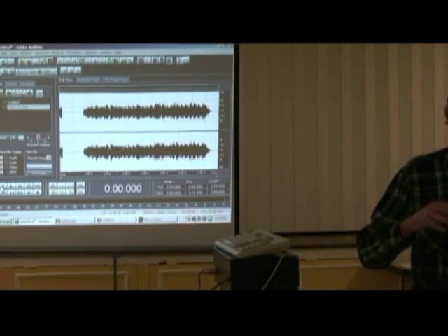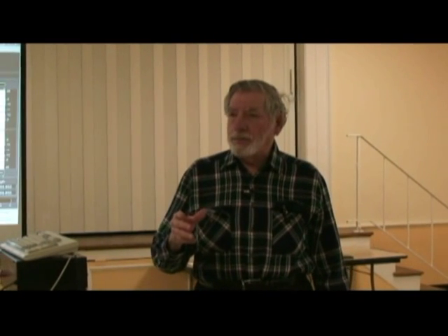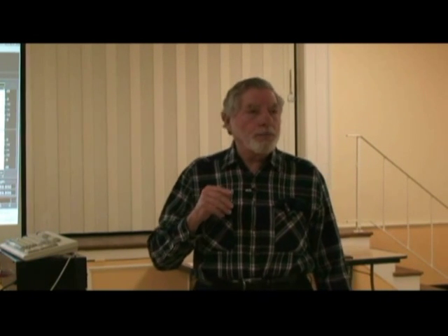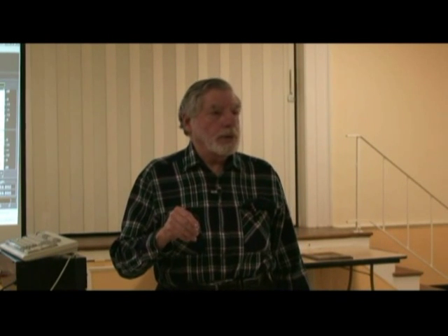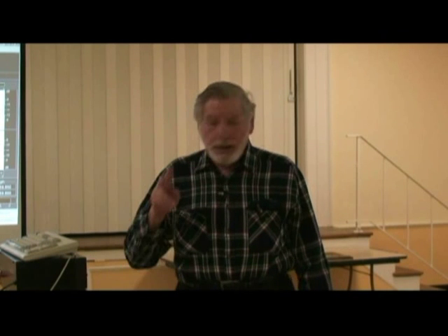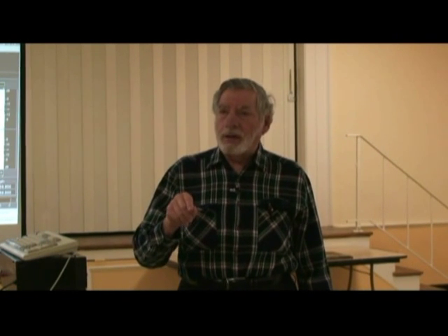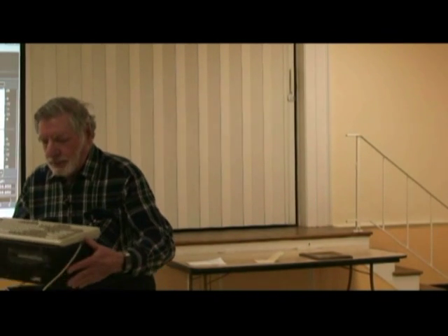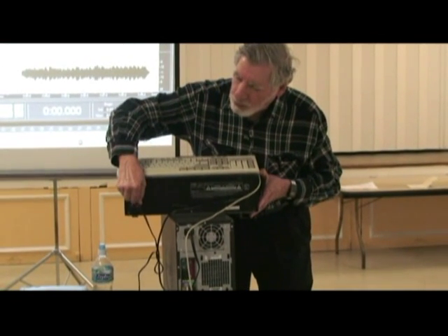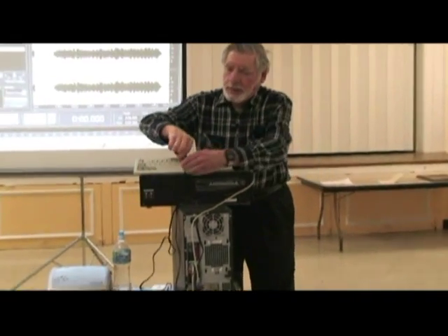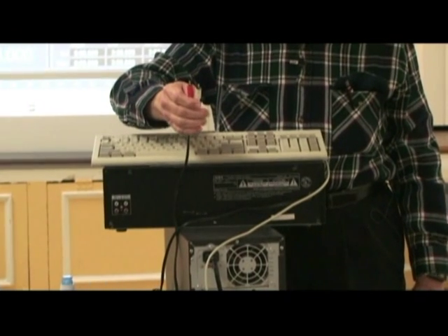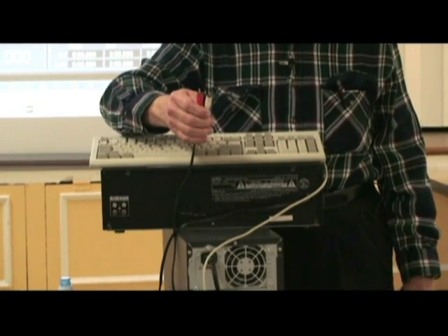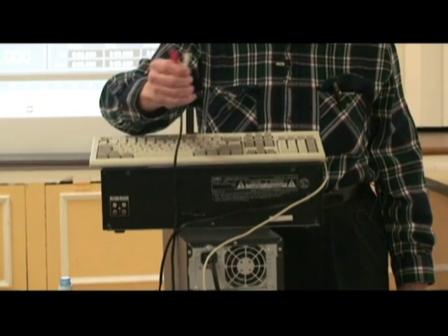But the audio cassettes, all the audio cassettes have 2 tracks. So even if it's monaural, your equipment is picking up the 2 tracks. If you have a monaural player, like a portable player that just has 1 output, it's not stereo, then what you need, I didn't bring that, you need a Y connector, which is an RCA plug. Let's see how you want to do this. If this had only a single output on the back, instead of left and right channels, if we only had 1 channel, then what I would buy is an RCA connection that had a Y connection with 2 RCA female jacks on one end and a male jack on the other. What I'm holding in my hand are male jacks.